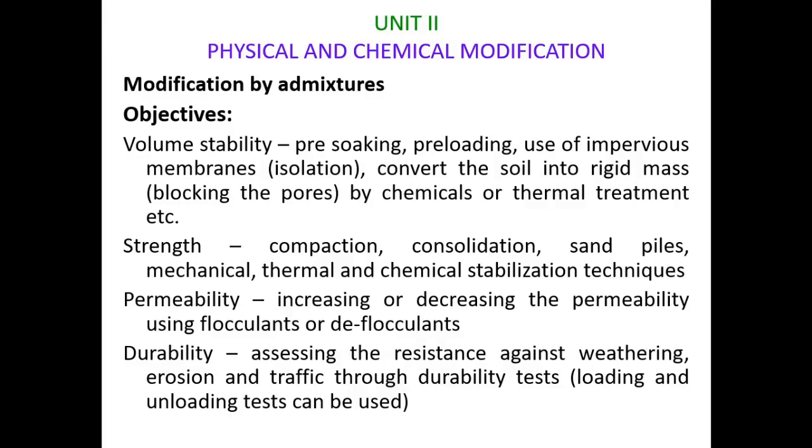The deformation of soil due to volume changes by moisture variation is similar to the deformation of soil under external loads. Therefore, the stabilization methods used to improve strength of the soil also improve its volume stability and vice versa. The common cause of low soil strength is poor drainage. The strength of soil is important for the construction of buildings, airfields, tunnels, etc., which can be improved by improving